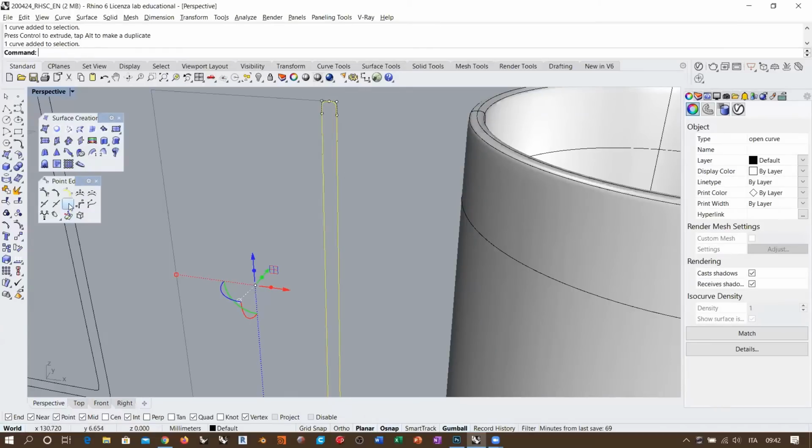So eventually I go here, I start adding, well, in this case, for example, it's irrelevant if I add knots or control points, because the curve is so flat that if I want a set of control points in this area, even if this is a smooth curve, it's probably the best way is to use an insert control point.